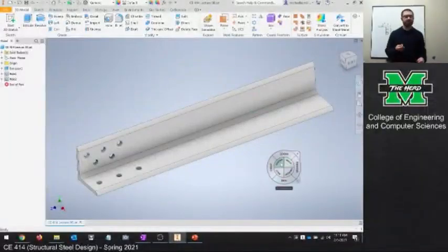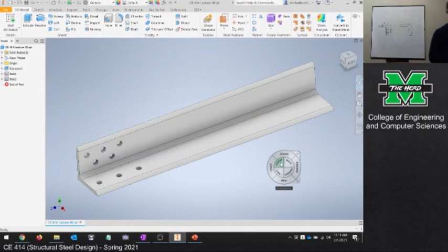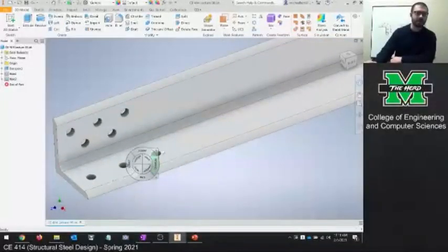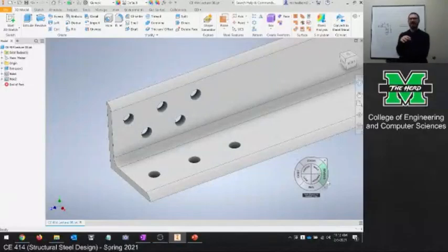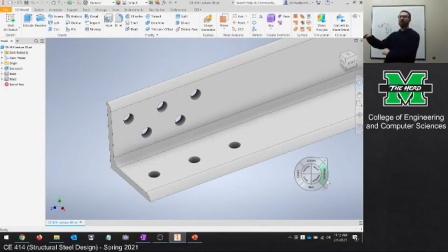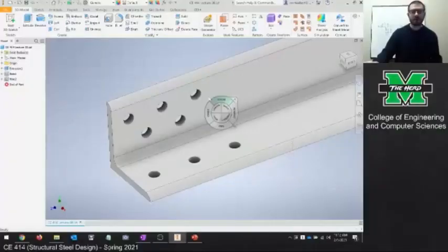And here with the class being operated virtually, I thought this would be a good thing to break out. So this morning I drew this part in 3 dimensions. This is kind of what you've got going on. Let me zoom in over to the connection. What makes this complicated is that the stagger is now crossing over from one element of the cross section to another. So how are we going to compute the stagger factor?